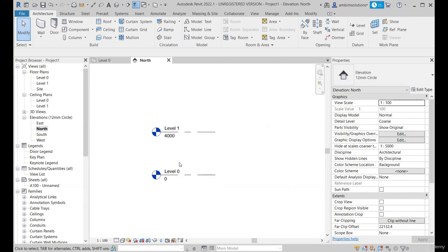If you have hundreds of projects on the same line, you won't be going and creating 5 levels of each 3 meters floor to floor height every time for all hundreds of projects. For that case, you will just create a single template file wherein you will have the basics by which you will start your project, and you won't have to repeat all the basic preparatory stuff again and again for all those hundreds of files.